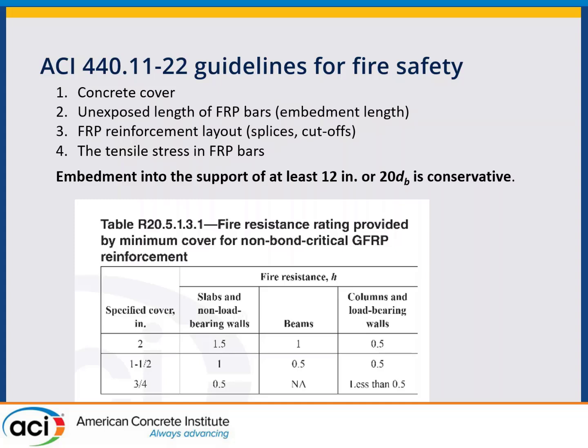45%. It was 45% of the ultimate. So typically, in a steel reinforced one, you might get closer to 60% of the ultimate. So we were lower than that, but still, you would never want to have a slab design that had those loads applied on it, because the deflections were very, very large for the span, and certainly a lot of cracking. But it certainly shows that doing this is going to be very conservative, because we only had 8 inches, and we're suggesting at least 12 inches, and into these cool zones.